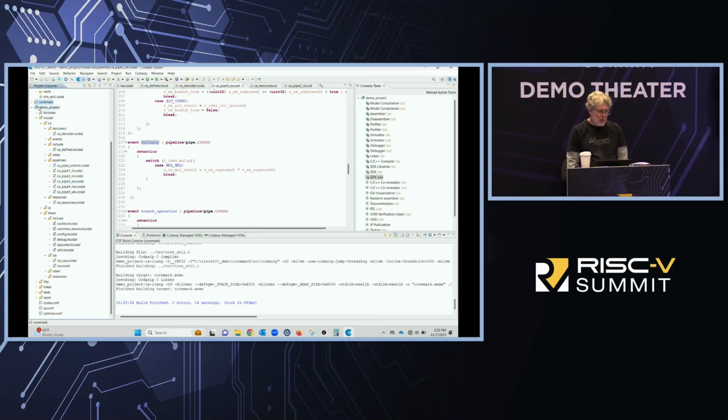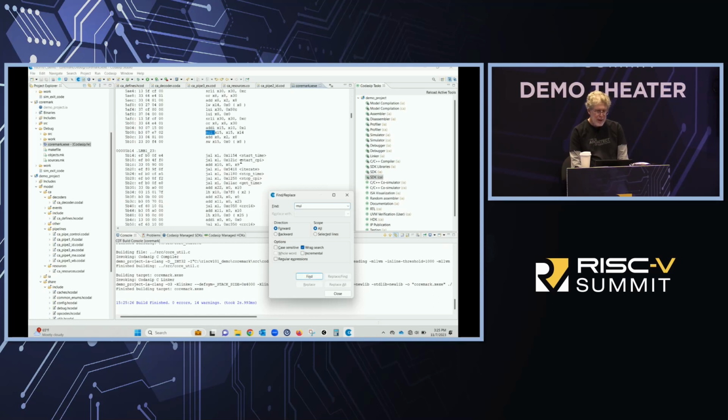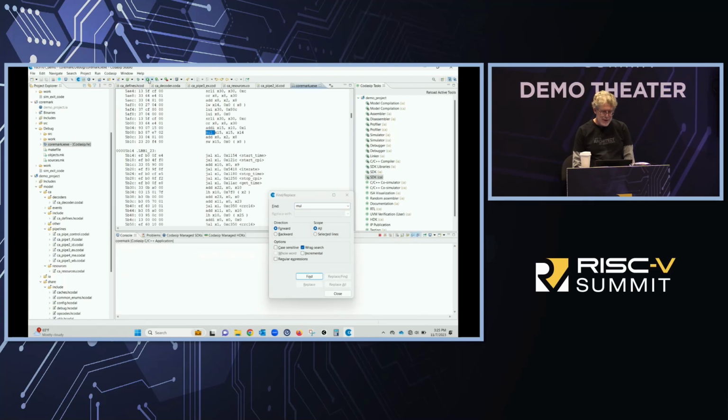And let's see, go to CoreMark, disassemble it. So you can see that my compiler now is recognizing the multiply, right? Just like I did when I did the mask operation, right? So now we're going to run it, and hopefully I got the CA model right. It should take less time because that's why I added a multiplier, right? A multiply compute element. So it will take 15 minutes or so.